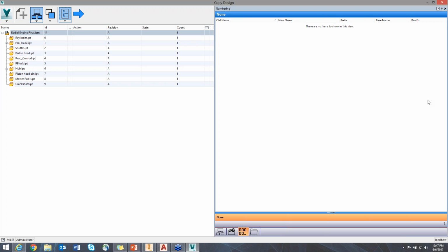In addition, Vault 2018 restores action rules mapping to name or file names, and allows action rules to be used across different vaults, assuming the property definition exists. It lets designers set target file properties to like properties of prior file revisions. And like I mentioned, it preserves Inventor iLogic rules on copied data. There are also improvements for the copy operation of files with linked drawings and more.